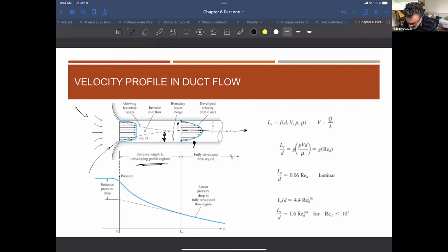Okay, the distance between where the fluid is coming from the tank with all the disturbance, as the fluid tries to get inside this duct here. You know what will happen in the beginning, there is going to be some kind of turbulence happening, and that's why you will see the velocity distribution here is almost flat in this case.